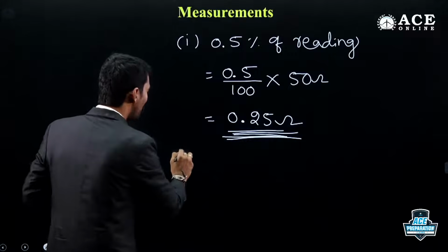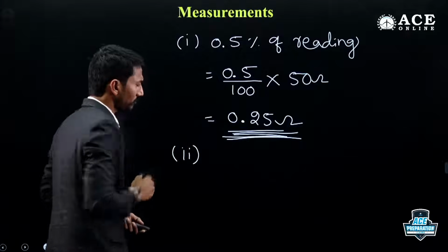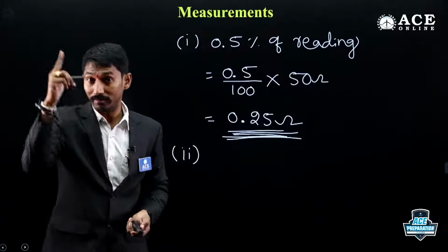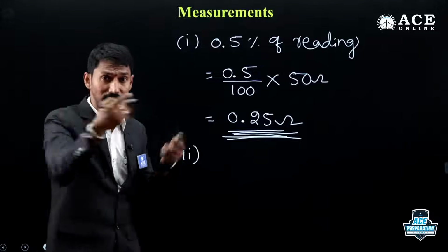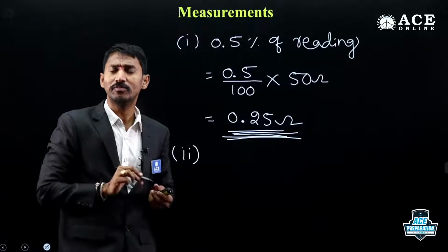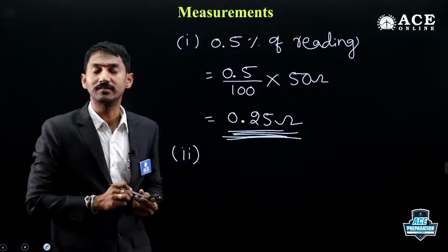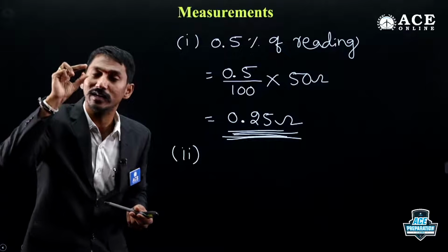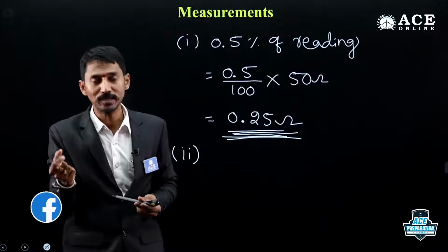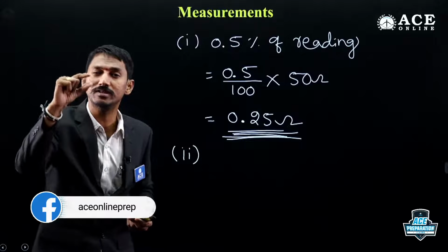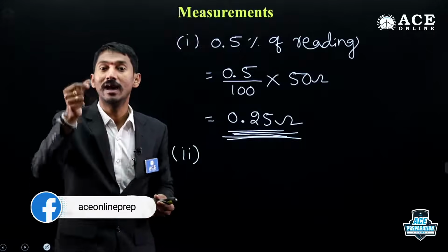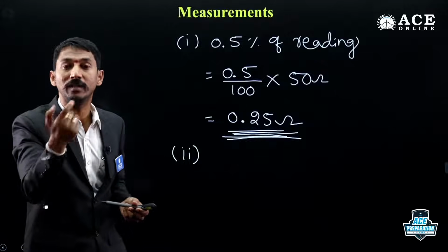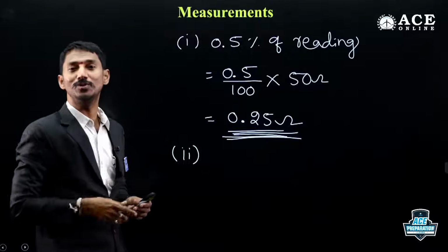But very important point, concentrate. Sir, in this, what is the meaning of count? While we were seeing the corresponding theory, generally count means resolution value, because it is the smallest measurable input change. In the digital voltmeter, generally one count, or one step in common language, is nothing but resolution.